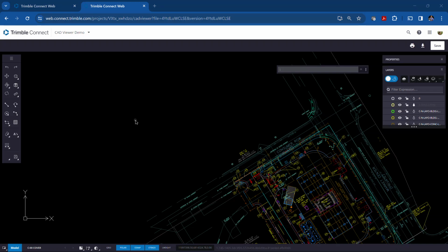So the next command that I'm going to talk about is the polyline command. You're probably asking yourself, what's the difference between a line and a polyline? Well, if I draw a line and I go from the start point to the end point, and then I draw the next point here, what I'm really drawing is two lines. That's a line that's got a start point and an end point. This one is a start point and an end point. So they're individual line segments.